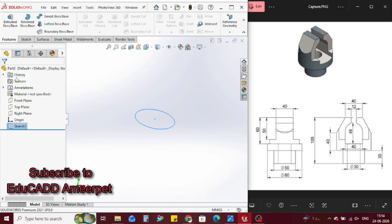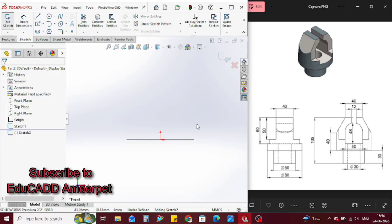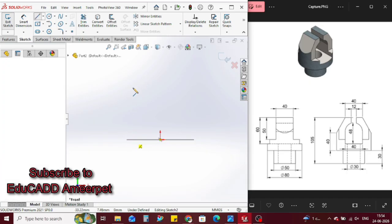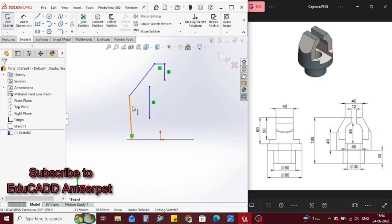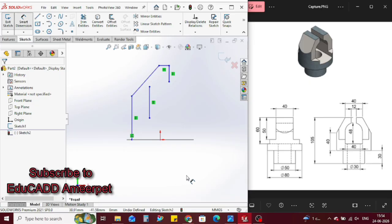I'm taking the front plane as an example, as a sketch plane. After that, whatever sketch is there, you can develop that sketch. I'm creating the shape like this, and I'll fix everything with the help of the dimensions. I'm creating the sketch manually like this. Okay, done. I want to make it a vertical line. I create the vertical.